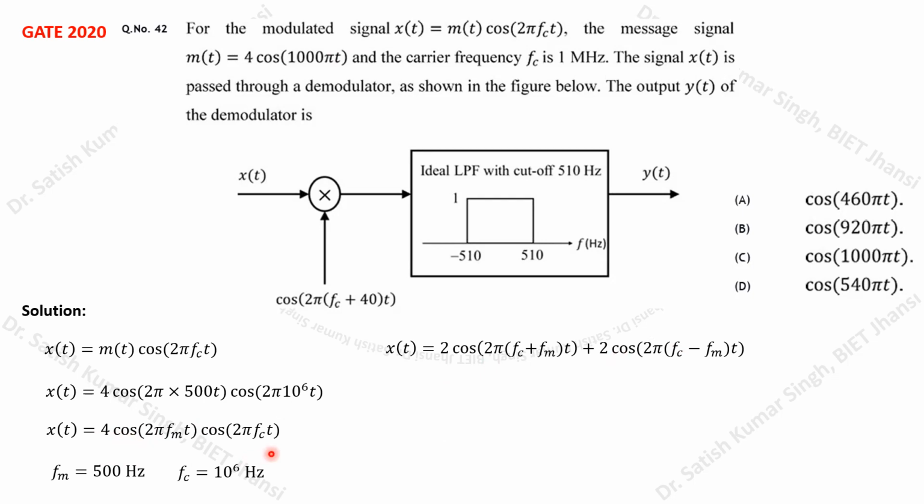So here we can see this is the x(t) term. Because this is our x(t) term, it has to be multiplied with this particular given carrier, because it is demodulating the signal. So this carrier has to be multiplied with this x(t) term. Here I have defined the output of this product modulator. After this multiplication, this signal I have defined as v(t). This v(t) is nothing but x(t) multiplied with this particular carrier. So that is the equation, and here we have to just substitute for this x(t) value.